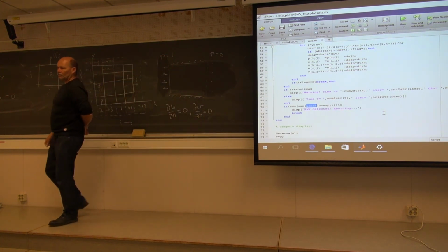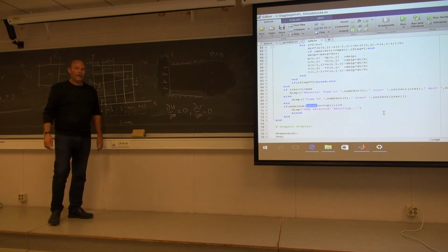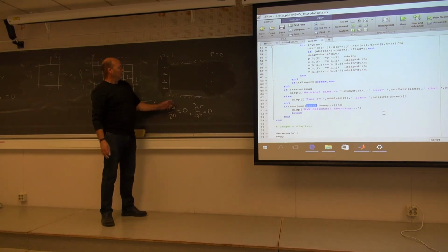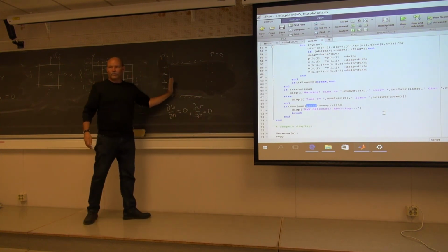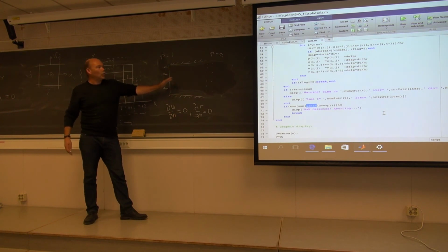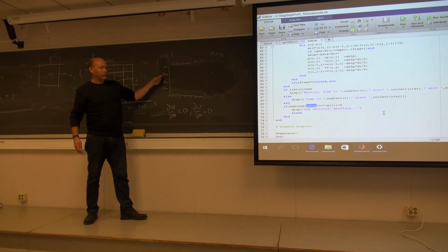That will not work, and that's not so easy to see. Remember, here I have now specified a pressure difference. That's a sort of driving force in the problem. Then you don't know how fast it will flow. That's a part of the solution. If I also specify the velocity inlet as well, then I specify too much. I'm going to strangle the entire code. It's going to explode.